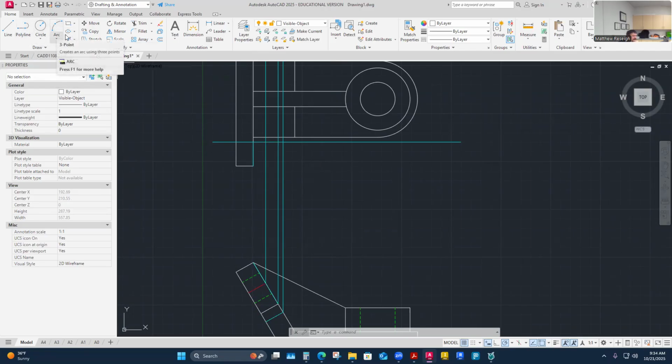I know we don't use arcs a lot, and you could piece this together with arcs, but you have this cool ellipse command that will either draw a center-driven ellipse, or an axis and an end, or an elliptical arc. So let me just choose the first one, center. And I'll just follow the command. Specify the center of ellipse.